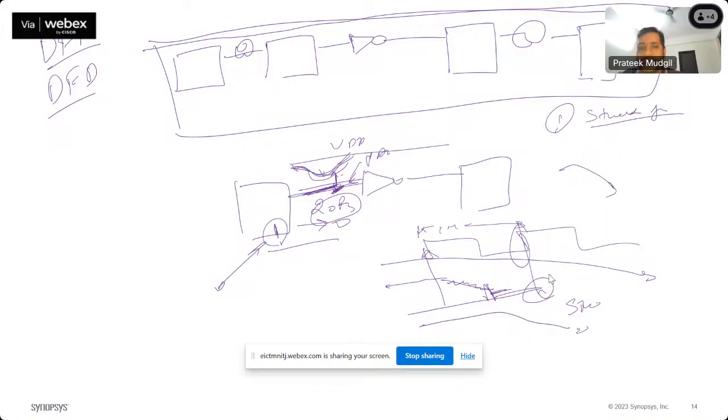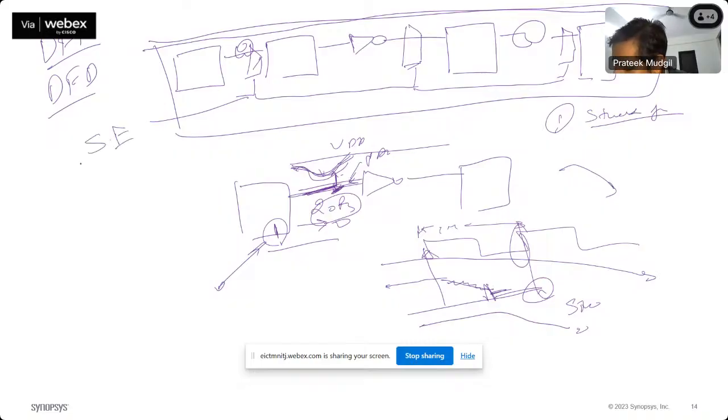So okay, how does ATPG scan chain work here, right? So what they do, let us say we put a mux here, right? We put a mux everywhere. We put a mux here. These are the muxes we are putting, right? And these are all scan enables. This is a scan enable port, scan in, and this is, let us say, scan mode, right?